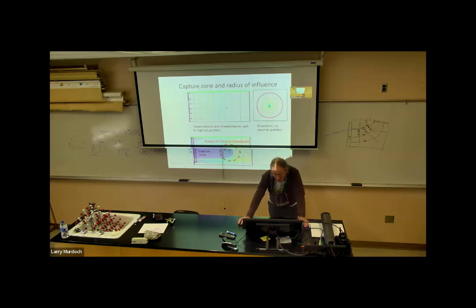Out here, the well is changing the head in the aquifer, but it's not capturing the water there. So if you had a monitoring well here, you would see when this well was activated, there would be drawdown. But it's not enough drawdown to capture this regional flow.